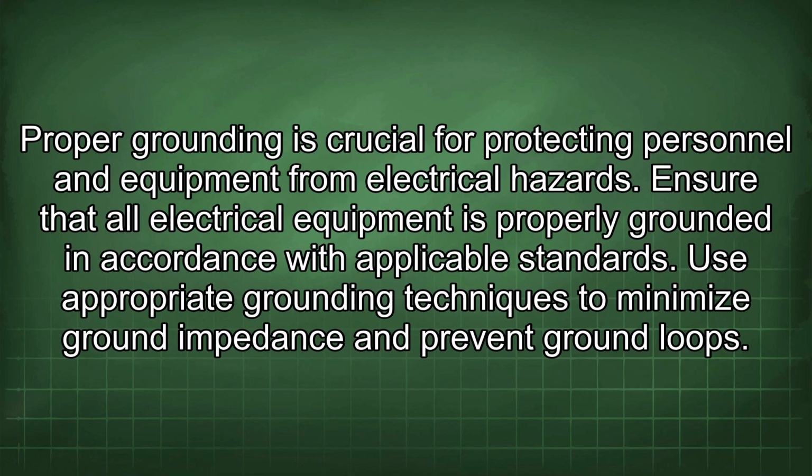Proper grounding is crucial for protecting personnel and equipment from electrical hazards. Ensure that all electrical equipment is properly grounded in accordance with applicable standards. Use appropriate grounding techniques to minimize ground impedance and prevent ground loops.